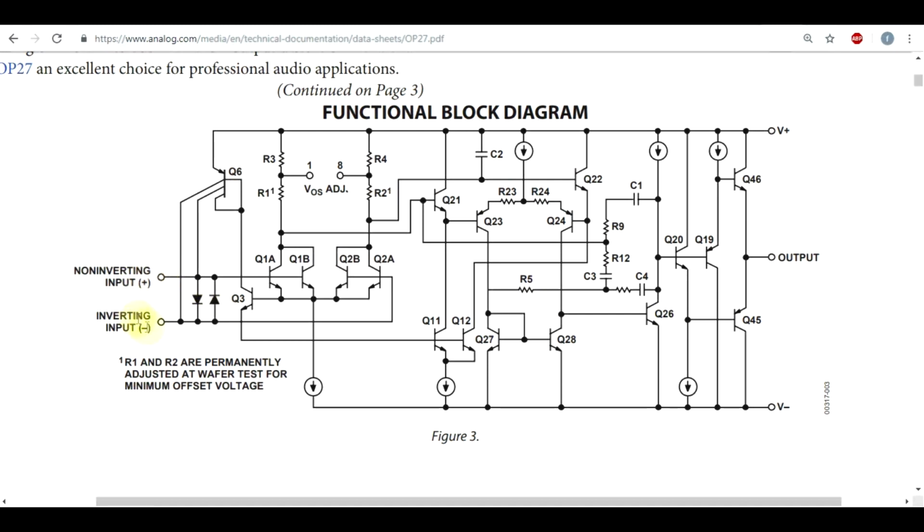First of all, if the difference between your two inputs is very large, then you're not really using the op-amp as an op-amp, you're using it as a comparator. So you don't really need a proper op-amp for that. Secondly, these input stage transistors are highly sensitive. Now, in general for a transistor, the collector-emitter voltage can be quite high, in the order of dozens of volts or even hundreds. But your base emitter voltage, the forward bias one is 0.7, but the reverse bias one is always a small voltage. It's in the order of a few volts.